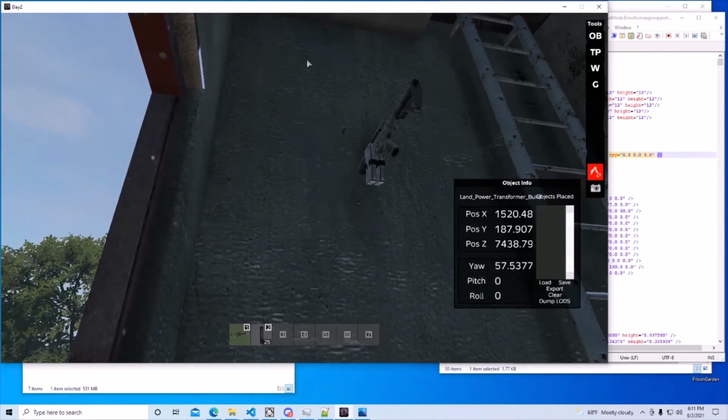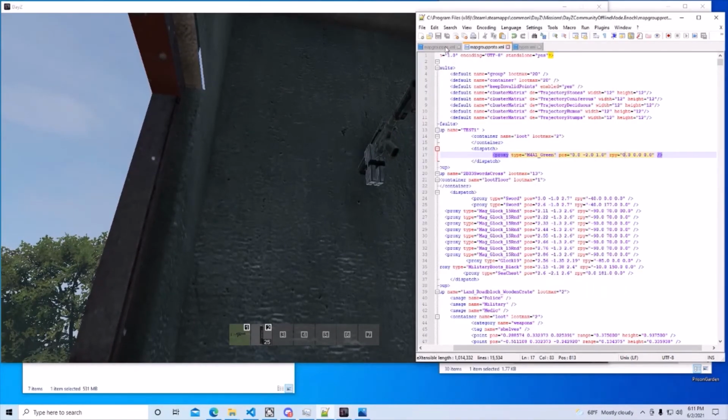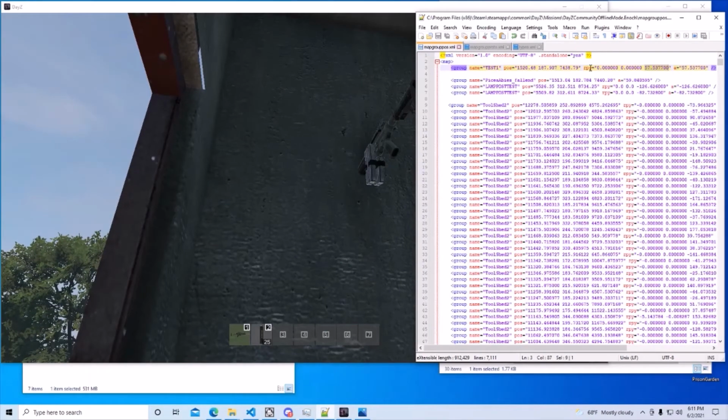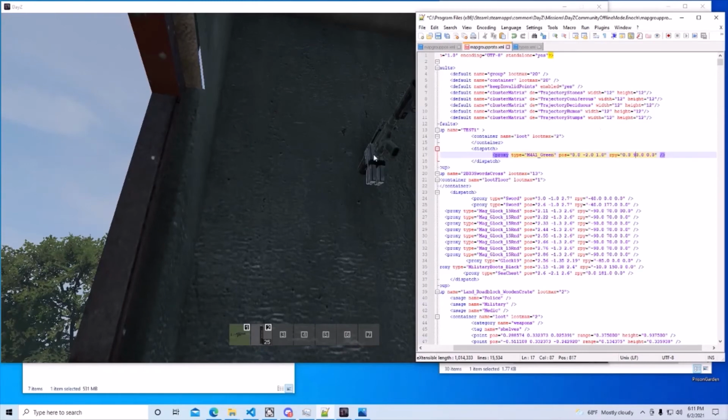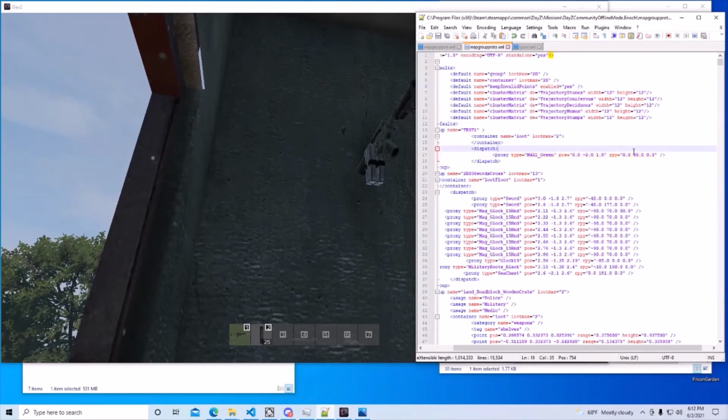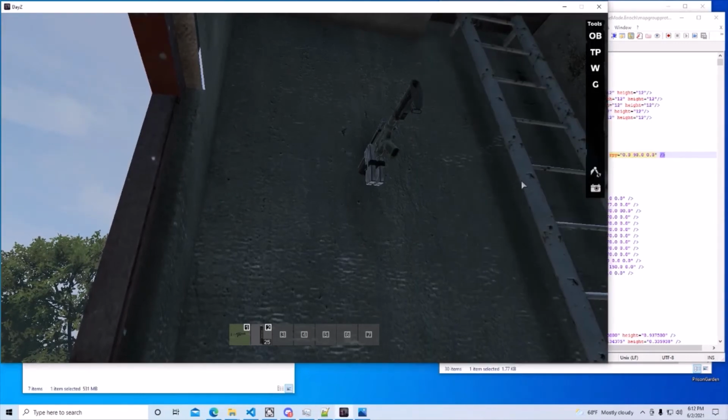sometimes it'll allow you to click on it, click around it, most times not. So we're trying to change our yaw, and like we've seen in the map group position, our yaw is actually back here. On the RPY, our yaw is here, and it's not the first one. So just remember that. Actually, for some reason, it says yaw RPY, like this is the yaw, but what we're going to be changing is this one here. So just bear with me. This is your yaw in the middle, and we just want to change that to 90. Depending on which way, like barrel left or right, it would be negative 90 or 90, but I'm not sure on that right now. So just 90 degrees should rotate it 90 degrees. And then we'll hit another restart after we save it.